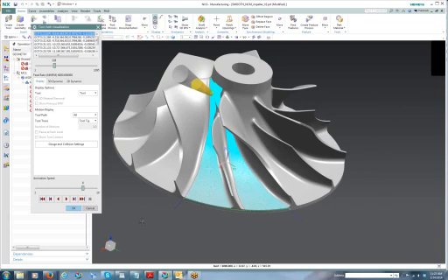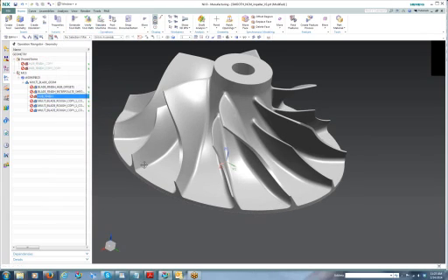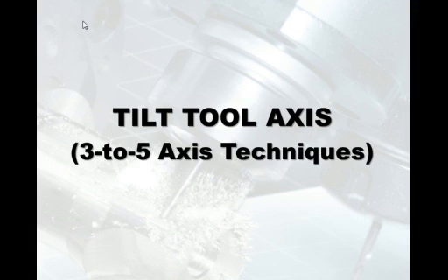You'll just have a lot of inefficient tool path, and you won't always be able to run these stiff cutters, so you're going to have to take lighter cuts, and your cycle time will be much longer. Also, it's very difficult in other systems to make money on just this one or two parts. You need a longer run because there's so much programming time involved.